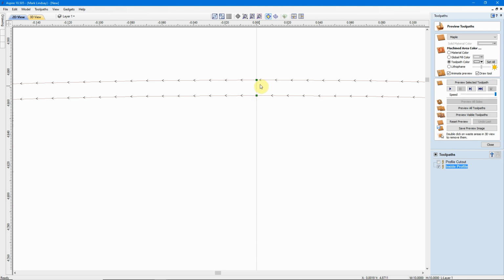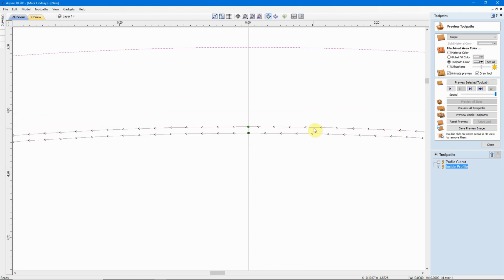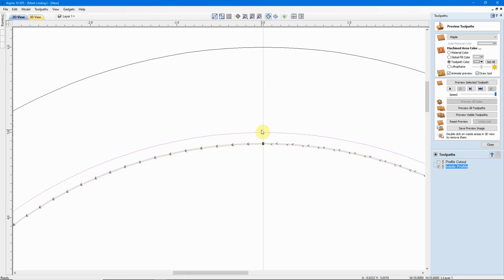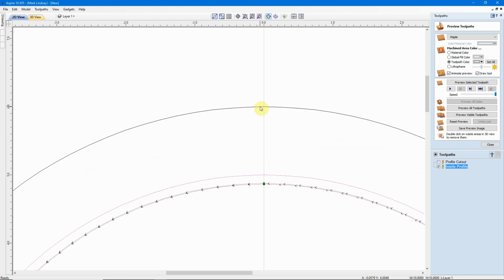Then retract out of the material, move over that 10,000ths of an inch, plunge down the full depth and make that last pass all the way through the material on this toolpath, cutting the entire thickness of the material. Work its way around until it gets back to this point, lift out of the material, and wrap it back over to 0. Same thing out here on the outside vector.